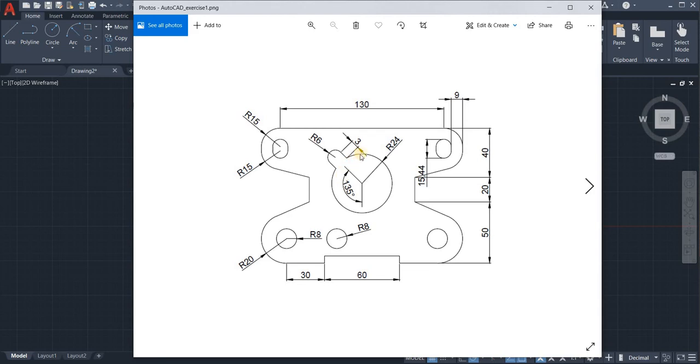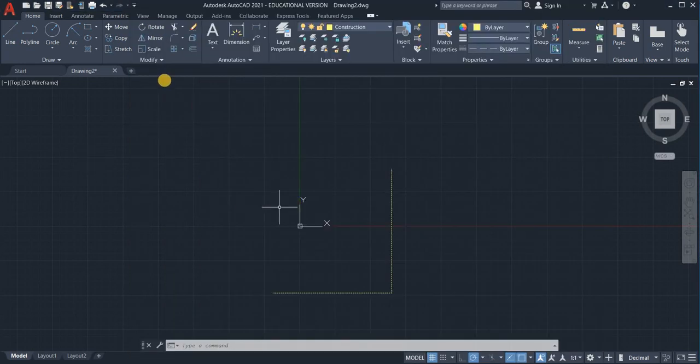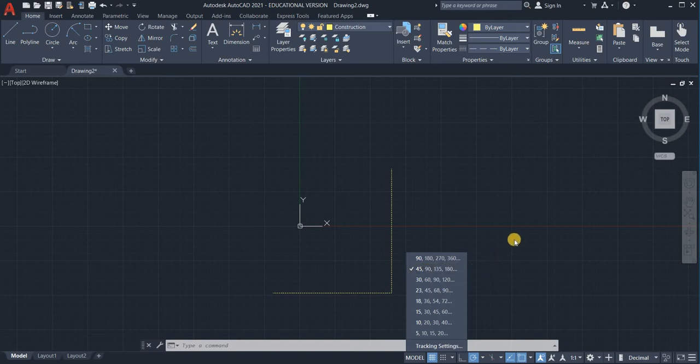Now a line, the total number of degrees for any line is 180 degrees. If I take 180 minus 135, I get 45 degrees. So keep that in mind because AutoCAD might show you a snap for 45 degrees before it shows you 135. Okay, so let's check our snaps. Go to polar snaps and we see 45, 90, 135, 180. Perfect.